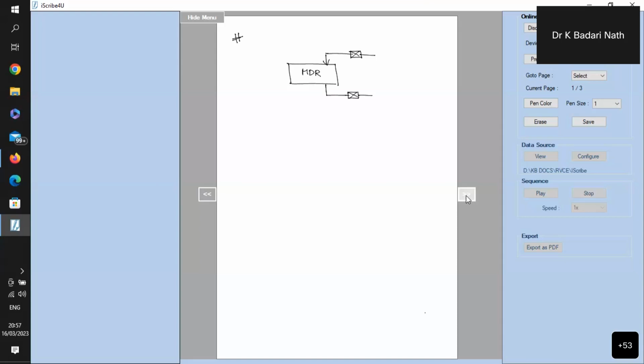So this is the processor side, this is from the processor bus. This is the memory bus, that is the external bus. That means what is there in the MDR register, I can write into the external bus. So a switch can be given to control that. This switch control I can call MDR out external, Out E. Out E is one which controls the external connection from MDR.